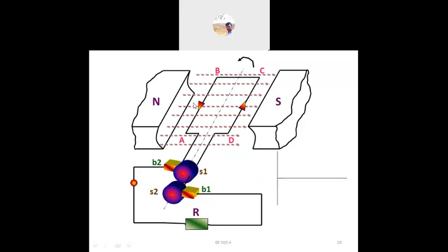When the rotation takes place from 0 degrees to 90 degrees, current flows through the coil. From Faraday's law, whenever a conductor cuts the magnetic field, some EMF is induced. You can see the induced EMF gradually increasing from zero, and at 90 degrees it is maximum.